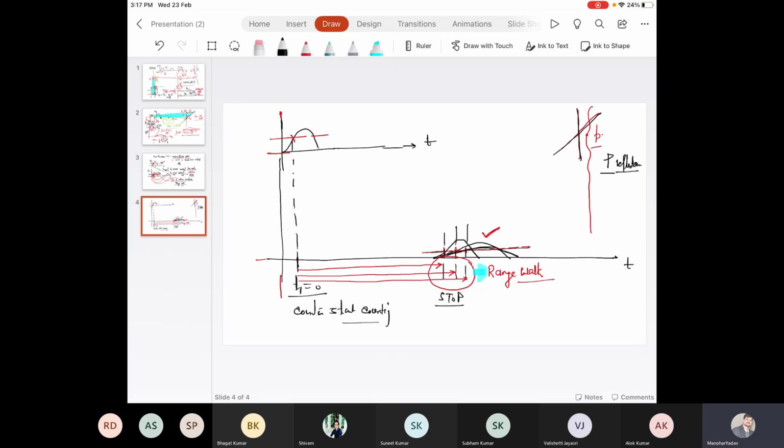When we use a constant fraction method, when this energy is received at the receiver, a threshold level VTH is defined. When that energy starts entering the receiver and attains this VTH, let's say for this return pulse, at this point a trigger signal is generated to stop the counting.